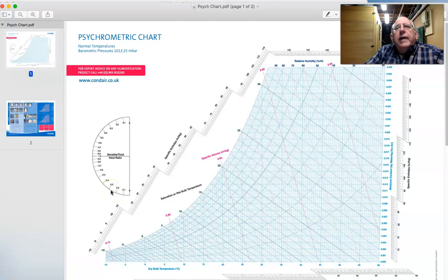If you had a straight edge and this protractor, you could start at this point and then obtain the slope of that process line that corresponded to 25% of the heat transfer being sensible and 75% being the latent component. And so these are some of the reasons why you see certain things showing up on a psych chart, these protractors and other things like that.